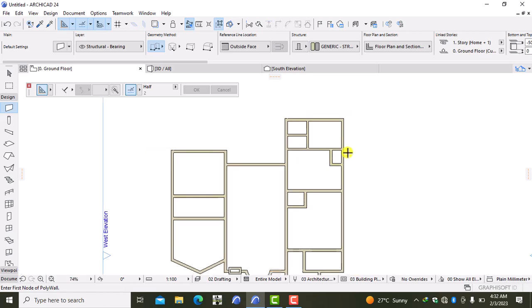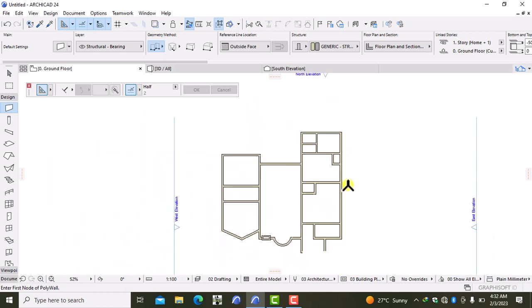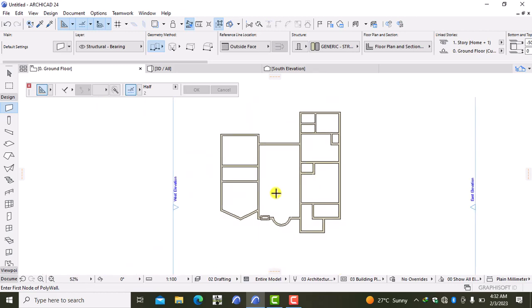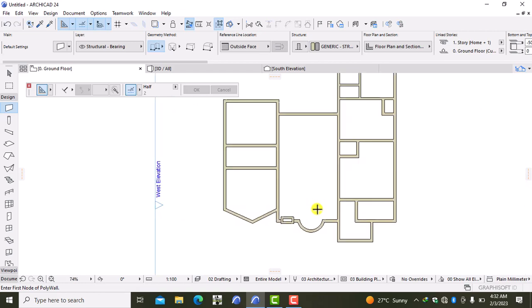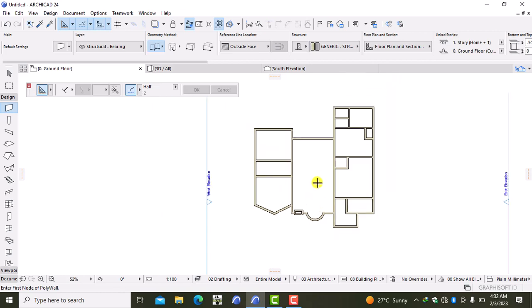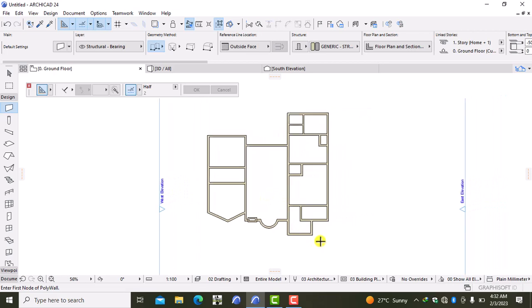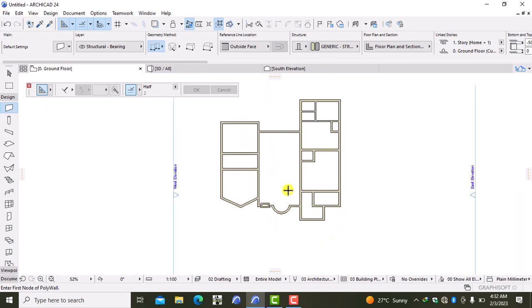Yeah. So basically, this is more or less the design of this particular house. This is the orientation of the walls that we have for this particular house. So just as I had highlighted earlier, for any kind of design that you want to do, it's very important that you first of all start by orientation of the walls so that you can lay out everything that pertains to the house, so that later on you can go and do the doors, which I'm going to do next in my video. The doors and the windows. We'll then go to placing objects. We then go to placing the roof and the slab, editing the elevations, yeah, and more of that.